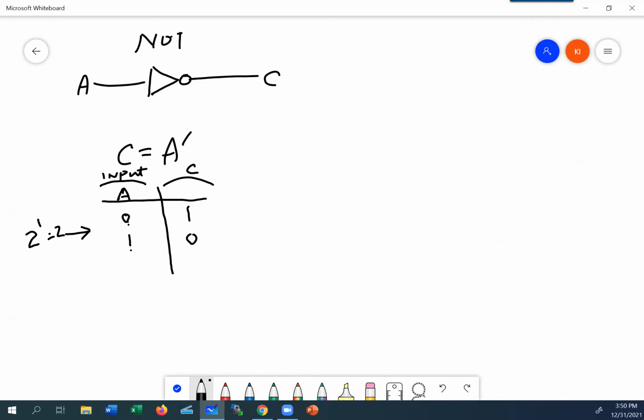Now, if you want to buy one of these and build it, you can go to a part which is either 74LS04, or its equivalent with the new technology of CMOS, 74HC04. If you're doing it in a classroom and we give you this to do, I like to use LS because it's hardier, so you touch it, the electricity in your body doesn't damage the part.